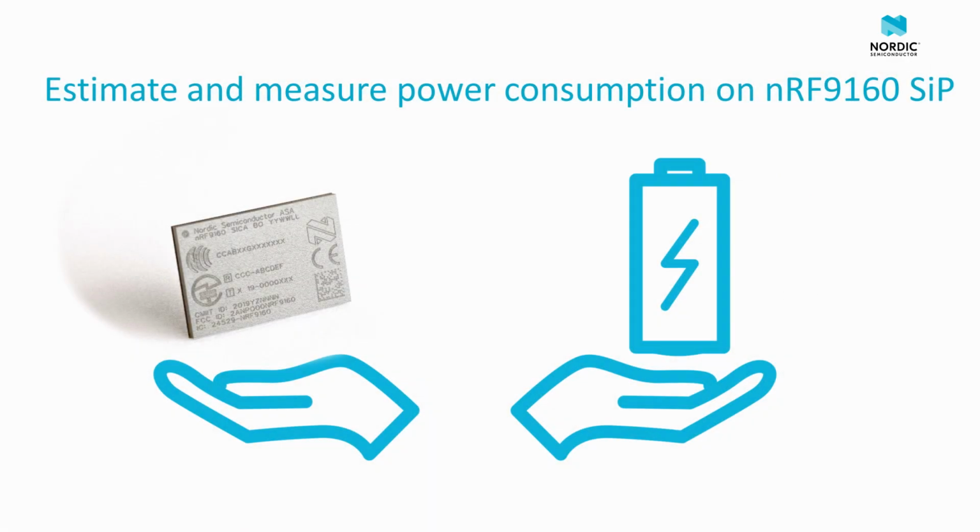During the next couple of minutes, you're going to learn how easy it is to estimate power consumption on the nRF9160 system in package using the online power profiler tool for LTE. You're also going to learn how to measure the actual power consumption using the new power profiler kit too.